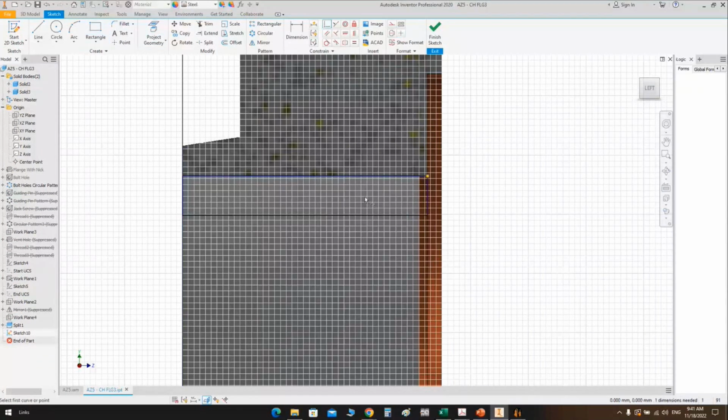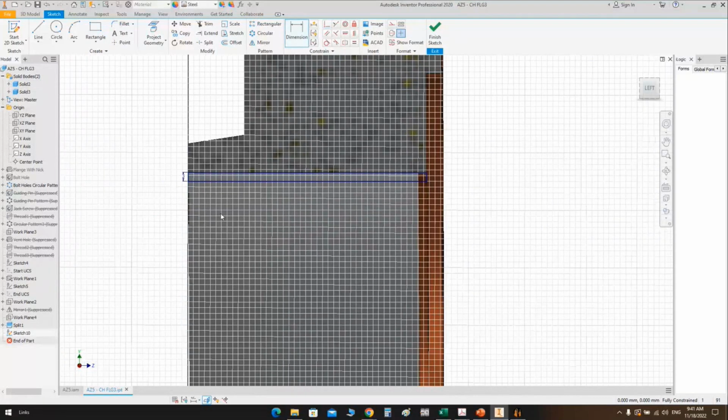define the clad thickness as 3 millimeters. And let's make the clad, and let's select the solid. It's solid 2. And from here, let's select the orientation X. So we have here a clad on this flange in that way.